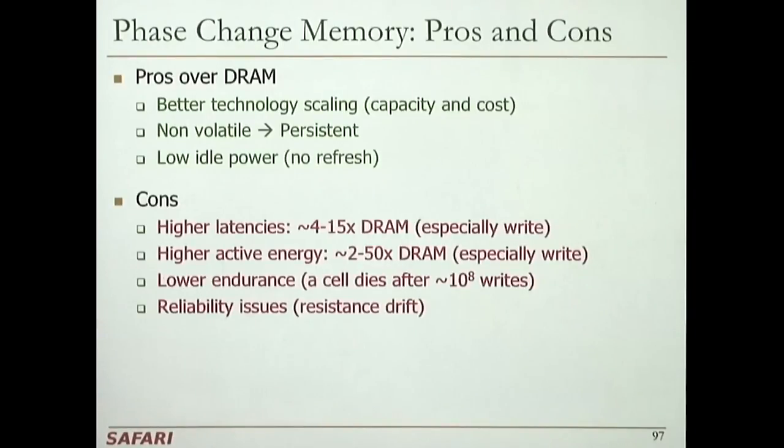So that's one potential reliability issue, but there are other reliability issues like resistance drift. For example, in DRAM, your charge leaks, but here the resistance actually drifts. It doesn't stay constant, so you need to actually refresh it. But the time scale of that resistance drift tends to be much larger than the time scale at which charge leaks. So that's a good part. You refresh much less frequently, every 3 days, let's say.